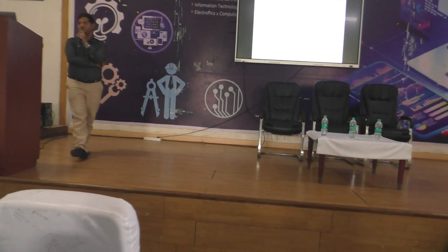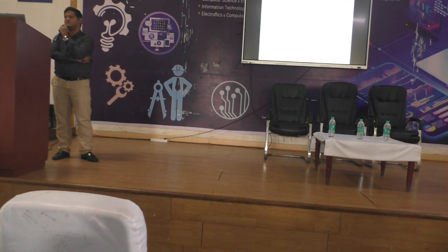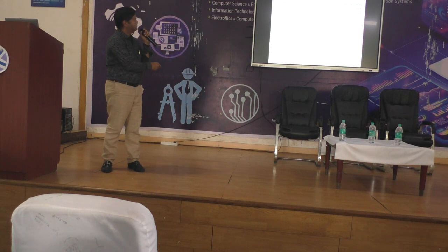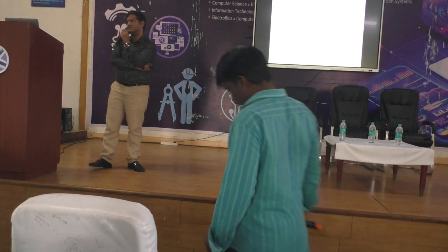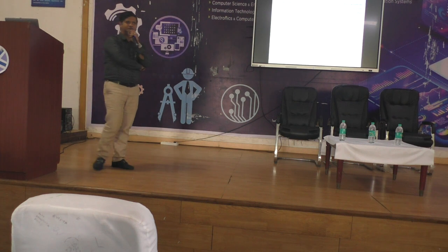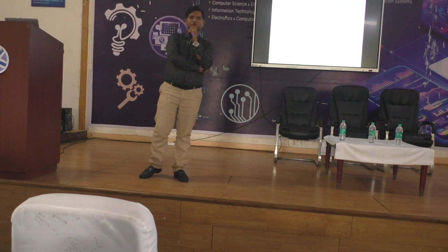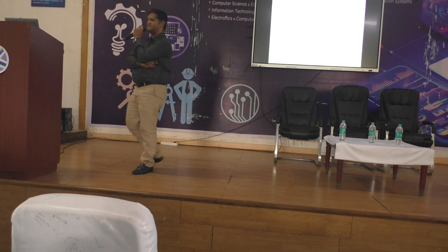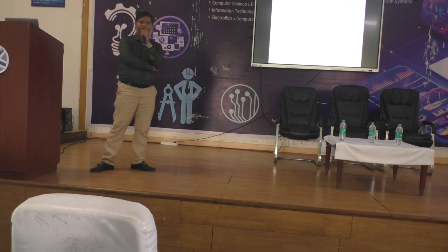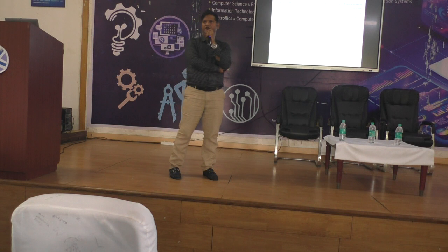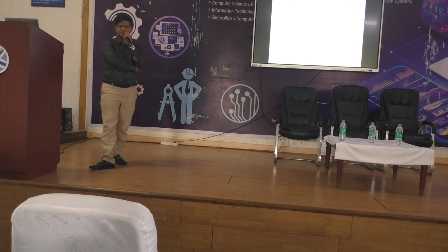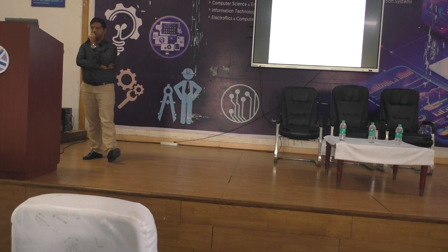So, as per ISO ASTM 52900, additive manufacturing can be defined as the process of joining materials to make parts from 3D CAD model layer upon layer. So it starts with a CAD model, you divide that into slices, and for each slice we try to make the path programming. As per the given information, the machine tries to deposit the material layer upon layer to make a 3D component. In simple terms, this is the definition of additive manufacturing.